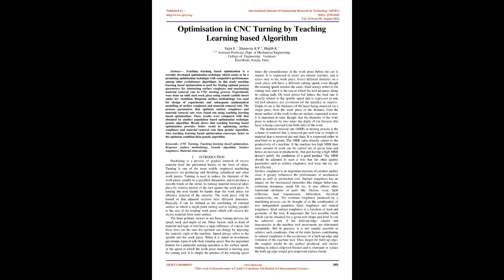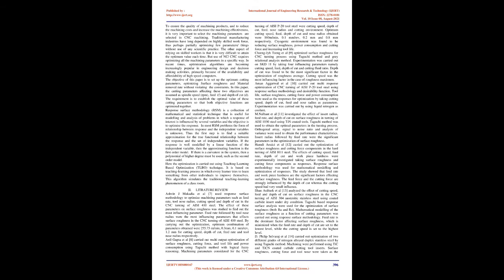If the machine has high MRR, then more amount of work can be carried out in given time and hence an increase in productivity. But just having a high MRR doesn't satisfy the conditions of a good product. The MRR should be adjusted in such a way that the other quality parameters such as surface roughness, tool wear rate, etc. are not affected.